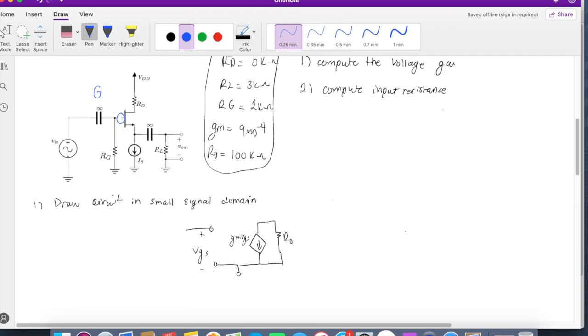Now, whichever component has the arrow, this is going to be the source. And whichever one is on the side with the two components, but does not have the arrow going in or out of the MOSFET, it's going to be the drain. So that's how we can easily tell. For AC analysis, it doesn't really matter, but to determine if it's an NMOS or a PMOS, the NMOS will have the arrow flowing outside of the MOSFET, but in a PMOS, the arrow will point into the MOSFET.